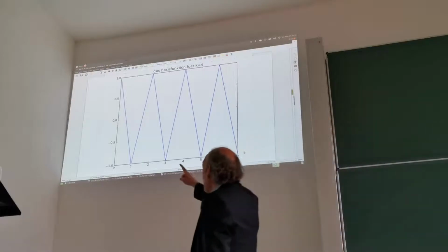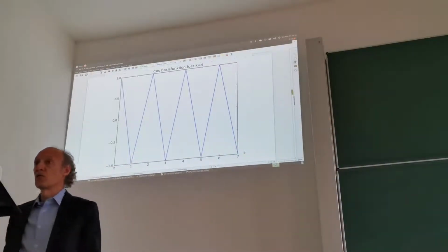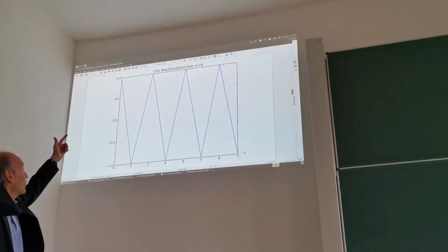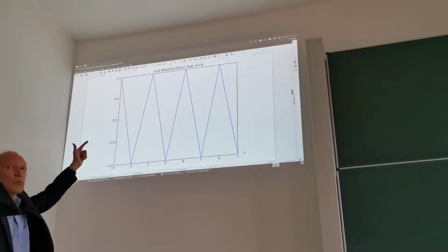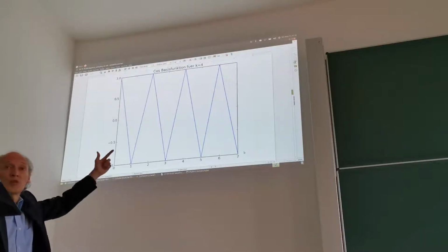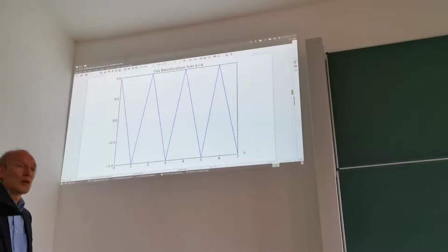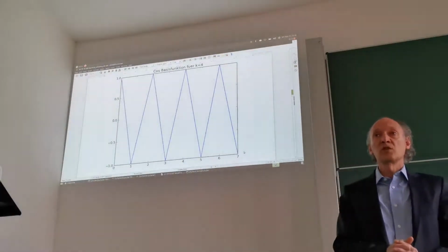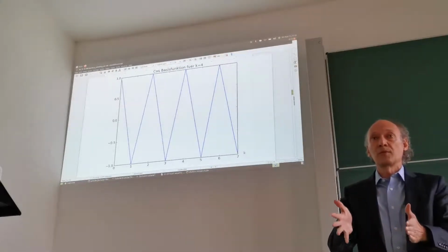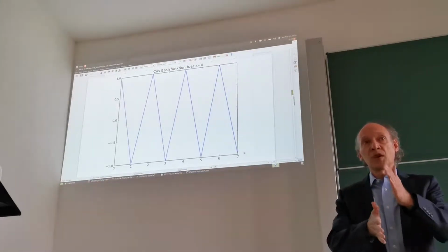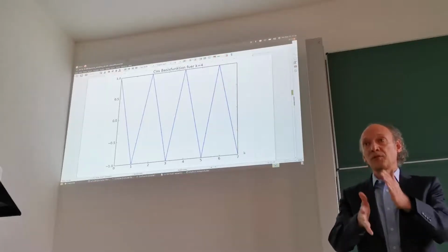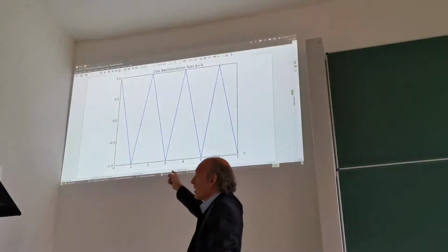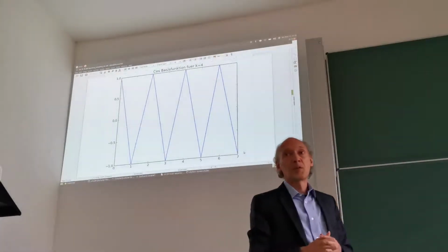So this is the cosine function for k equals 4, which is basically the Nyquist frequency. And you can see it just jumps from +1 to -1, back to +1, and so on. So it simply changes the sign for every other sample. And this is the maximum rate of change that we can obtain for a real valued signal. Right? We cannot change faster than from one sample to the next. And hence, this is the highest possible frequency that we have with this sampling rate, our Nyquist frequency.